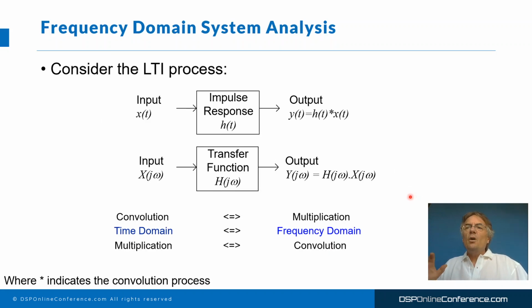So we can use a property of signal processing that convolution in the time domain is equivalent to multiplication in the frequency domain, and also vice versa actually. Convolution in the frequency domain is equivalent to multiplication in the time domain. But for our purposes, we're thinking about convolution in the time domain, which is this very mathematically or processor intensive task: multiply, accumulate, multiply, accumulate, multiply, accumulate. We can replace that convolution operation with a multiplication operation in the frequency domain.